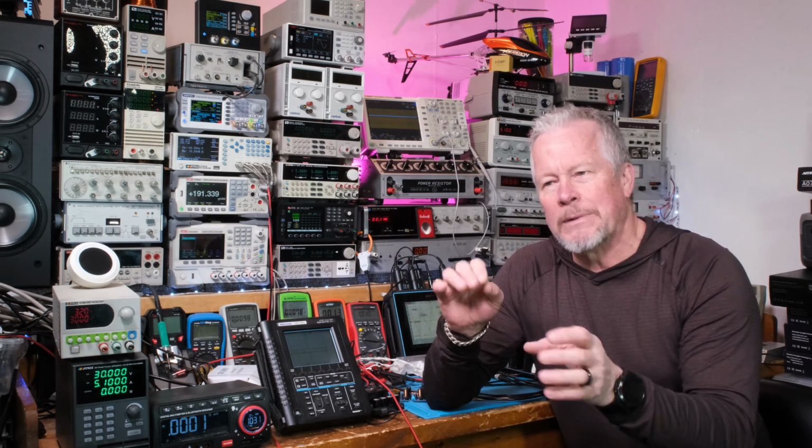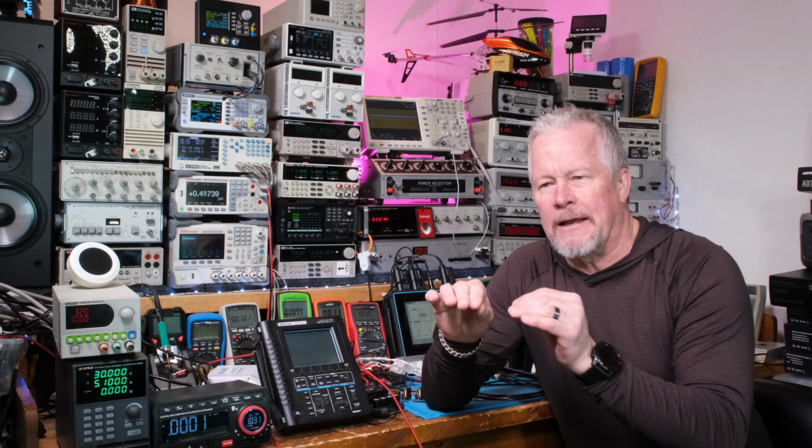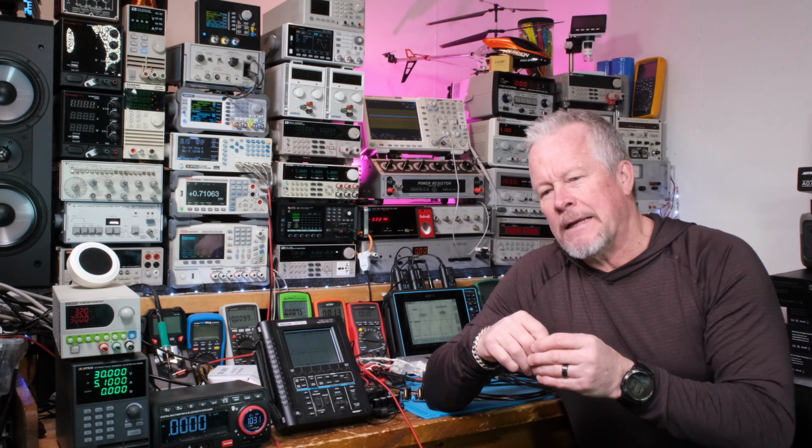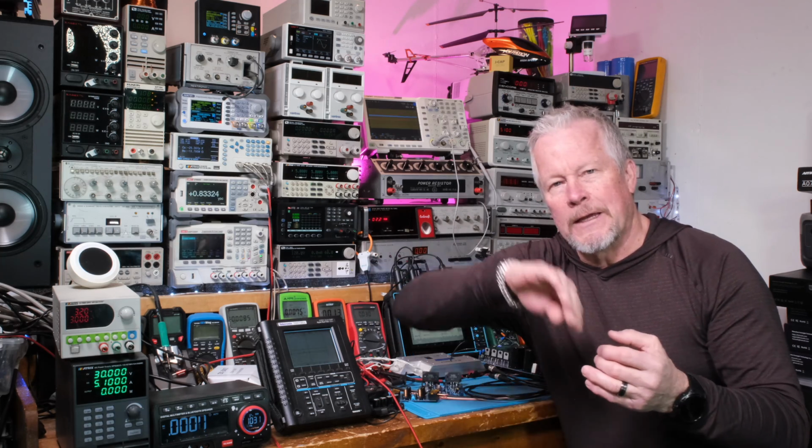Now what it is, it's creating models. So any kind of transistor really, whether it's a FET or JFET or even diodes. What's really neat about this tool is, in the past, when I try to create a model, if I can, I'll download the model, but then I'll go into each parameter and set it, and hopefully that's going to make this model representative of the real device so that it'll reproduce those curves that we see down below.